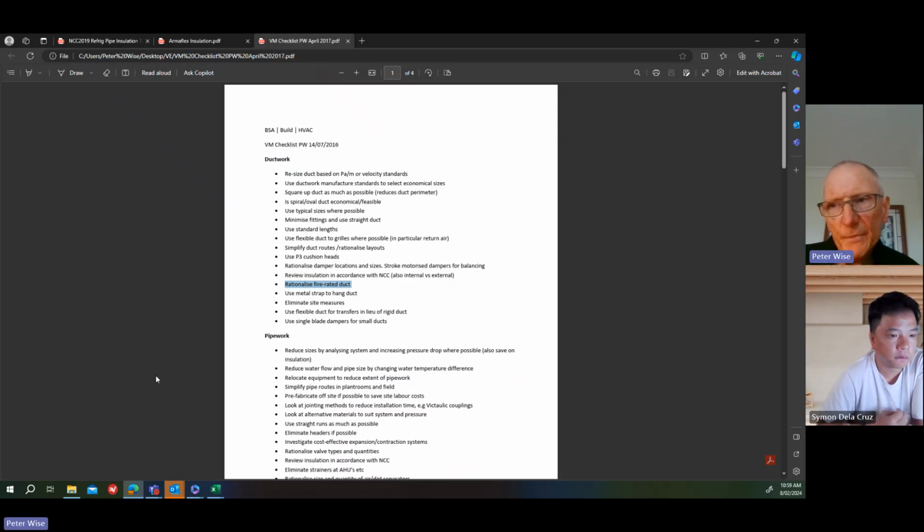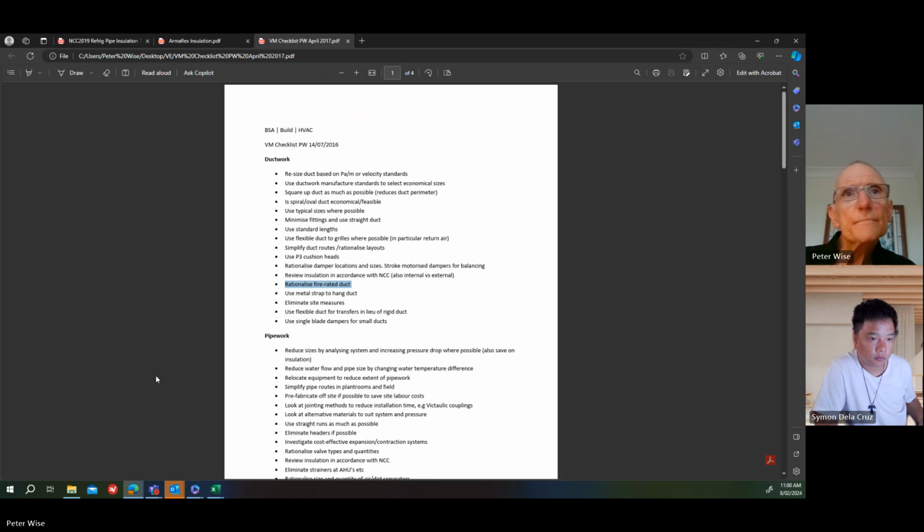But you also have to remember that sometimes in an air conditioning system, the fire wrap may also be the thermal insulation. So it has to comply with the NCC thermal insulation requirements. If it's an exhaust system, there's no requirement for insulation, but there's the requirement to achieve a 2-hour fire rating. But if it's a supply system, and you've got a complicated fire hazard or smoke hazard management system, the supply duct may be fire rated. It just depends on the building.